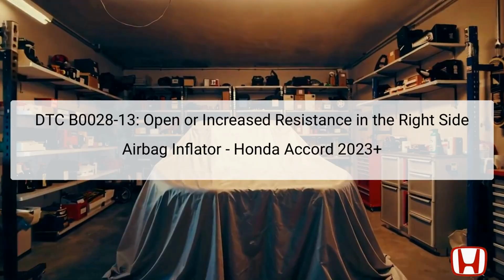The Diagnostic Trouble Code, DTC B0028-13, pertains to an issue with the right side airbag inflator in a Honda Accord 2023. Specifically, this code indicates either an open circuit or increased resistance in the airbag inflator circuit. The airbag inflator is responsible for deploying the airbag in the event of a collision, providing critical protection to the